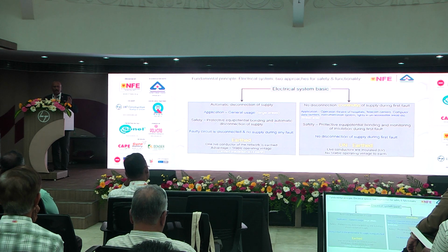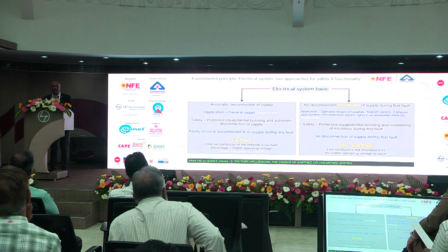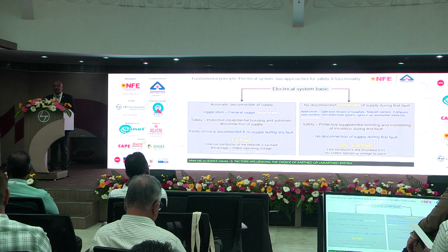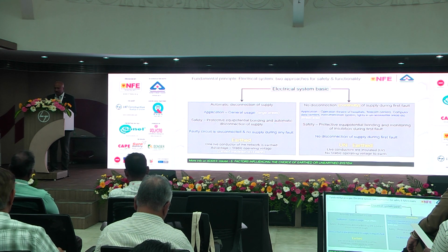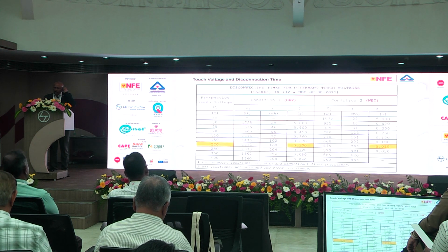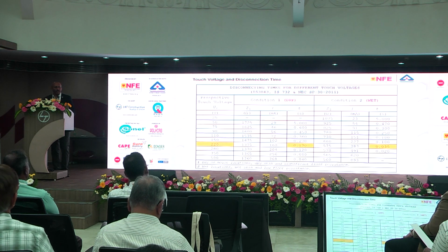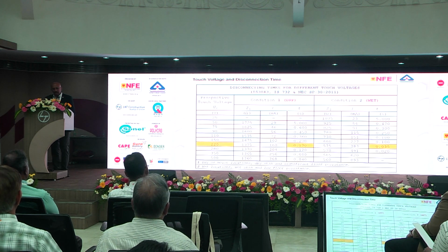These 2 are the technical requirements. Today we will talk more about the first one, which is the earthed supply, which we generally use in our electrical installation. You can see this information in IS 3043, clause 5. You can find more details about this particular requirement. If you look at NEC, part 1, section 18 or IS 3043, you can find this kind of a table which talks about the maximum allowed disconnection time.